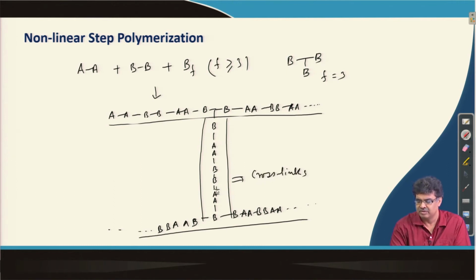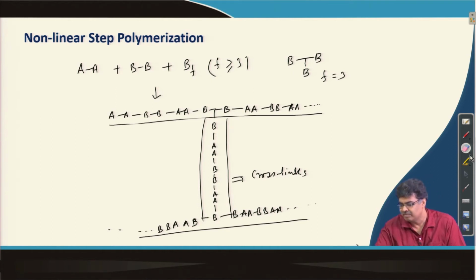So, we are getting a cross-linked polymer in this particular case. If the monomer ratio is such, or the reaction goes on for a longer time, then at one time it might happen that all the polymer chains can get tied up with each other through cross links, and you get an almost infinite molecular weight polymer, and we get a network polymer in this case.